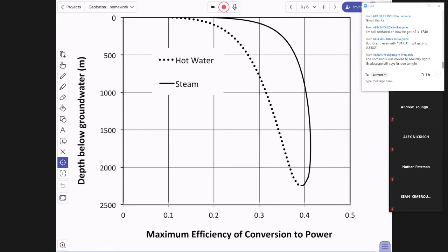Yeah. Let me explain that. That's an interesting segue to another interesting thermodynamic piece of this. The intent of what they've been doing on hot, dry rock, and I showed you where they were on the temperature scale, or where they were underground, they're all working on this line. They're looking at only liquids. So the transport of energy between liquids and the surrounding rock is really, really difficult because it's all going through fractures, right? So they have to put in a bunch more fractures to be able to get any heat transfer from that rock to that flowing water.